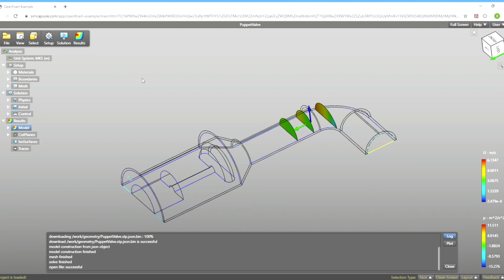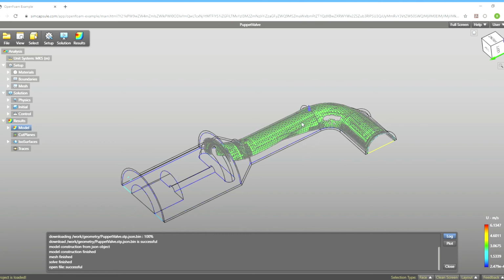To remove a filter, right-click, remove, select it. Either we could remove them by tab. Similar to cut plane, we can also add isosurface here. Edit, show pressure. Spin mouse wheel to change ISO value. Apply it.